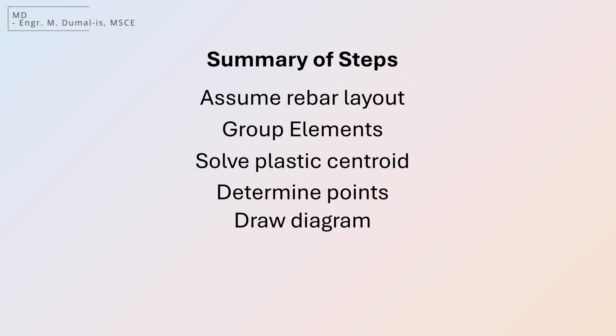Now that we've introduced the problem, here's the general outline of our calculation process. Based on the previous lecture, our first step is to assume a rebar layout. Next, we'll group the elements, solve for the plastic centroid, determine the key points, and finally construct the interaction diagram.